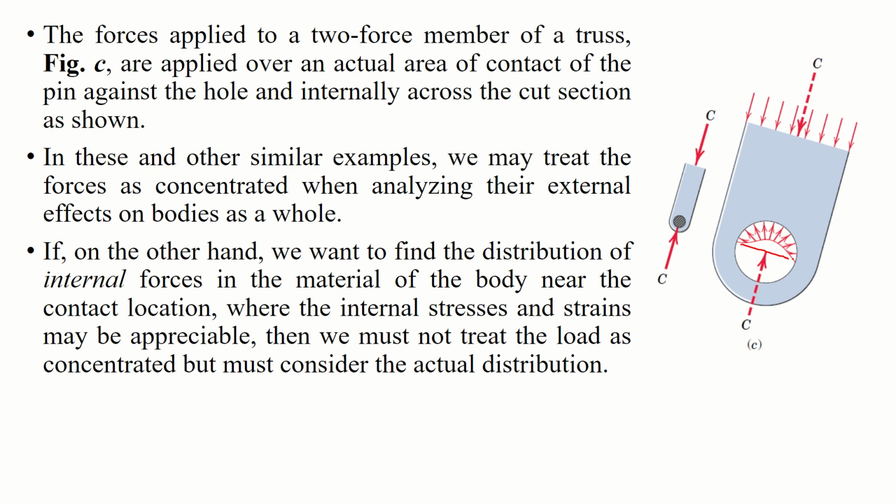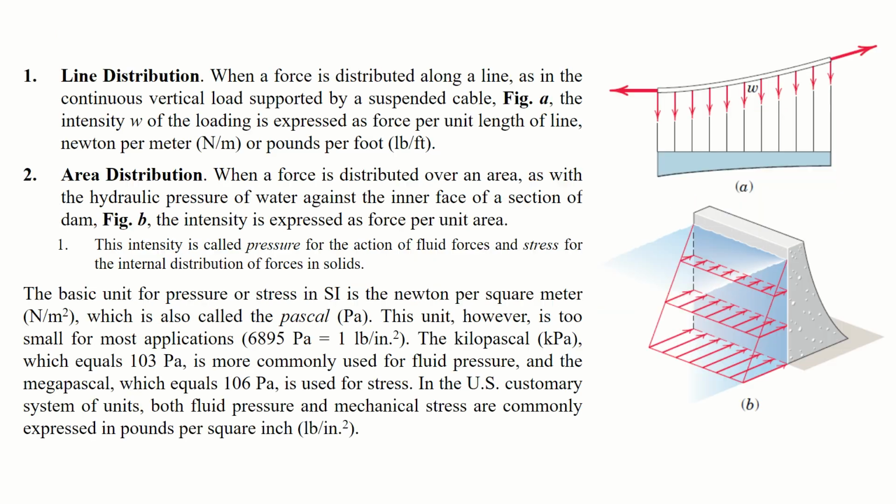When forces are applied over a region whose dimensions are not negligible compared to other pertinent dimensions, then we must account for the actual manner in which the force is distributed. The summing effect of the distributed force over the entire region is found using mathematical integration. This requires that we know the intensity of the force at any location. There are three categories of such problems, based on how the force is distributed.